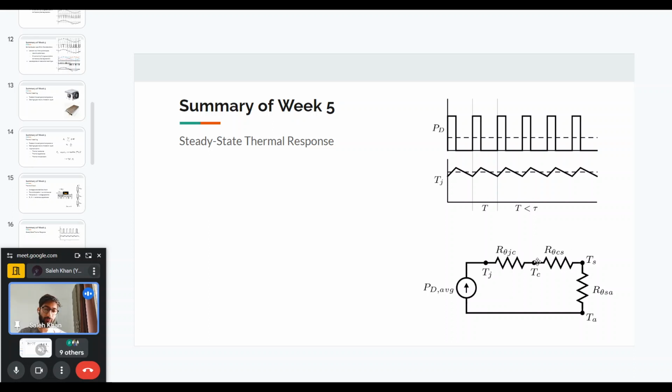And so we have to find its thermal resistance based on a separate data sheet. And finally, we have the heatsink, which is connected to this thermal interface material, and it is basically in touch with the ambient. And this will be the thermal circuit, and the temperature at each point is basically analogous to the voltage.